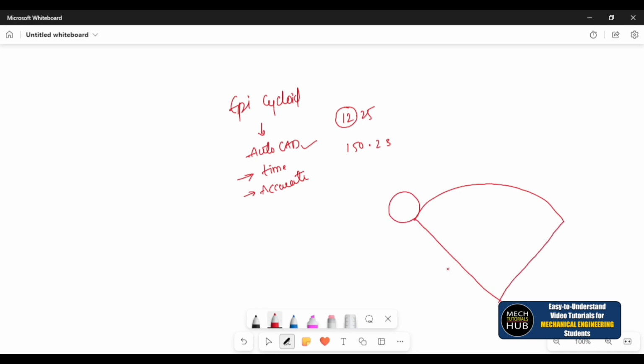Epicycloid is something, a curve is traced with respect to a reference point P when it rolls up to a distance of its circumference. Okay, when it rolls upon another circle in this direction, this particular reference point will make multiple markings or instances on its way till the end point. When you join all the points, that is going to give us the epicycloidal curve. Let us see this construction by using a software called AutoCAD.